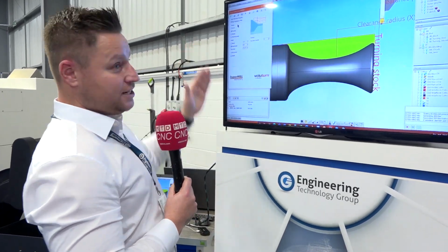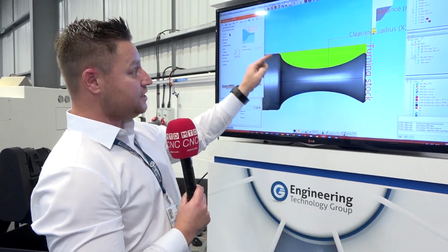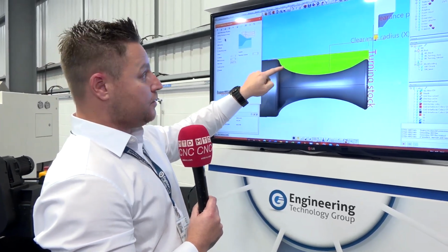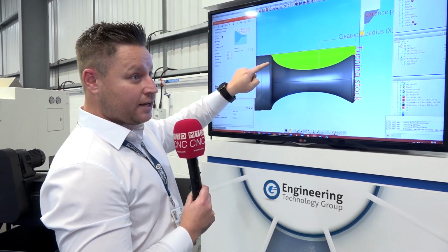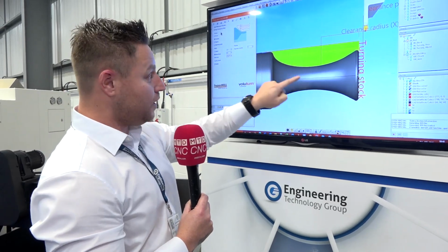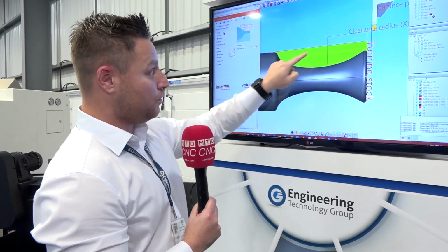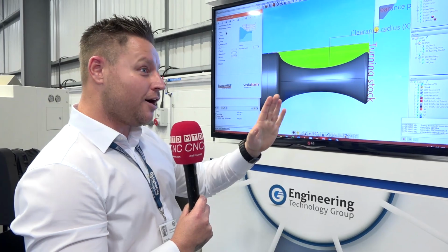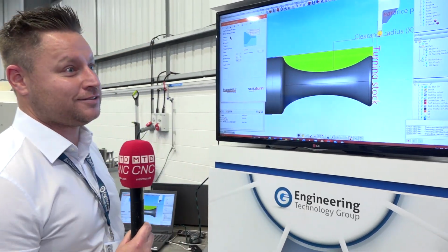And once you switch on zigzag, the tool will cut forward. If it sees a dense area that you're cutting, the tool will force its way down if it can. It will recalculate itself to find the dense area, and the zigzag will solve that problem for you. So now you get even less of a high feed move out.